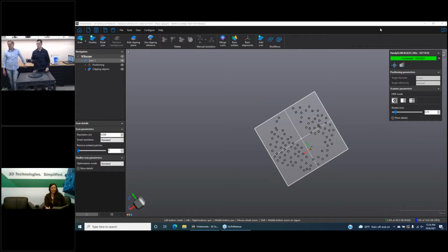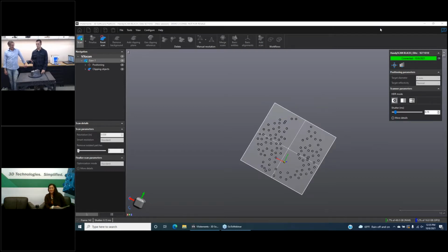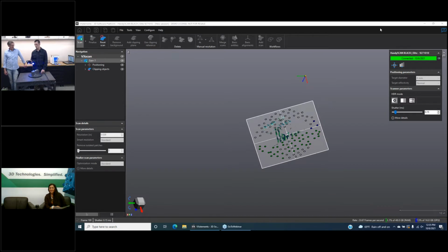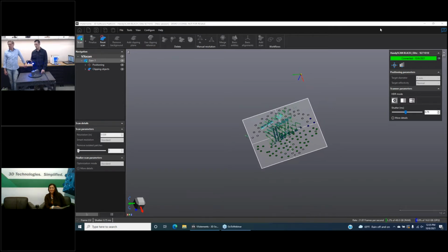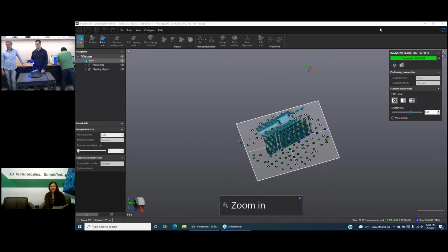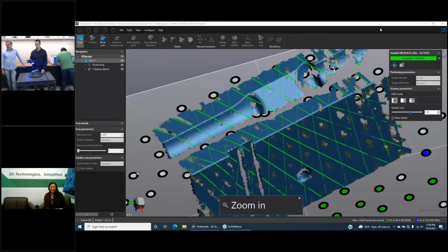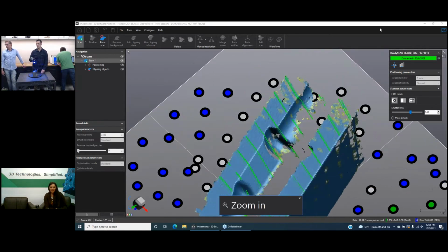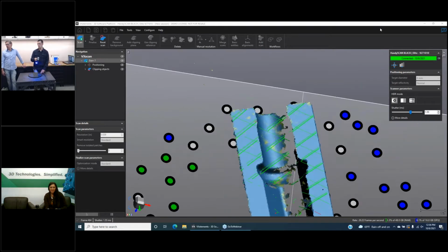I was saying that I love the finite details of that scanner, and it's great for small parts manufacturing, but as we all know, not all parts will fit into that scanning environment. So where do we go next? The next step would be the Handy Scan Black Elite from Creaform. It is a handheld, laser-based, blue laser scanner, and it's capable of doing not only small parts, but large parts as well.